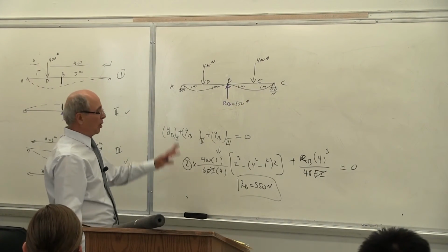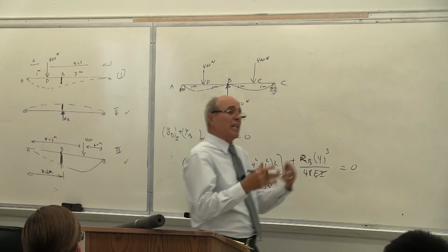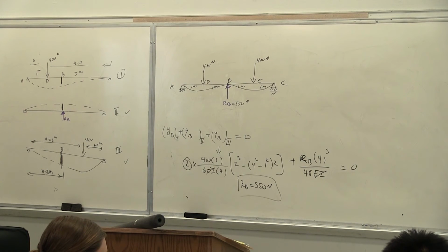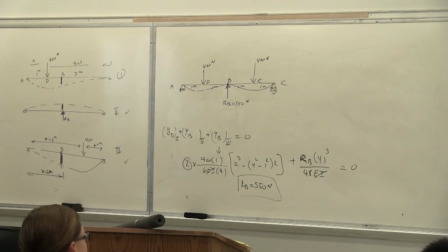Correct or not? So all this superposition, and practically every method, all the methods I give you, double integration, direct method, all of them, when it comes to the indeterminate problem, actually solve the static for you. Is that correct or not? After static is done, then you can draw your shear and moment diagram, then you can design the beam, and that's the end of the story.